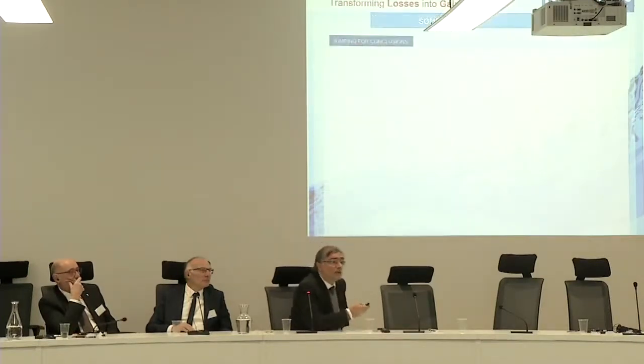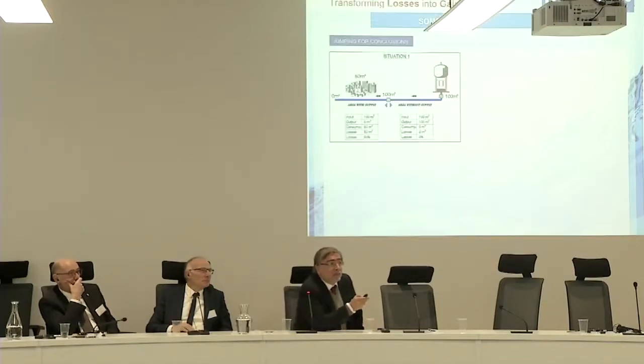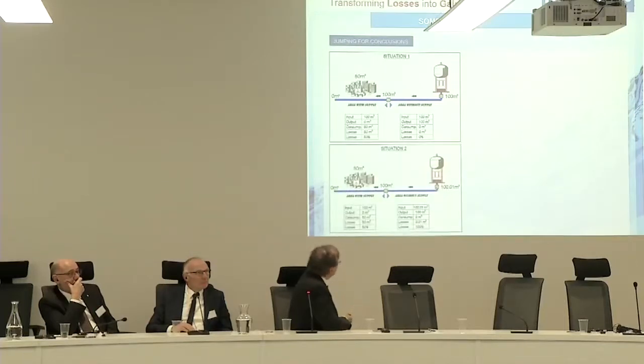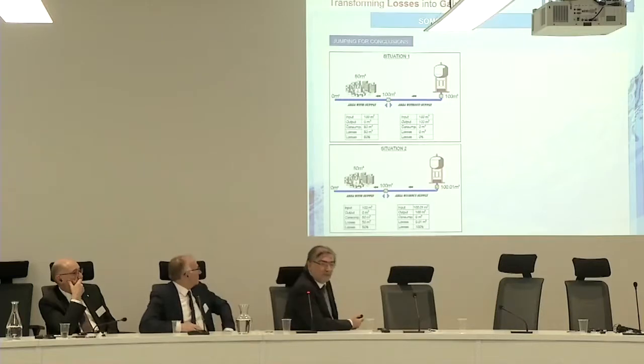Okay, the dangers of this index: jumping to conclusions. If you have a part of the system that has no consumption without supply, this says 50%, and this is very good, no losses. But if you lose a drop, it will be 100% losses. So we would say this is awful, this is marvelous, but it's not true.